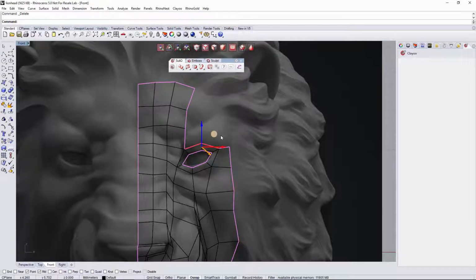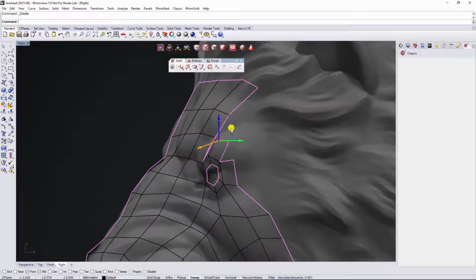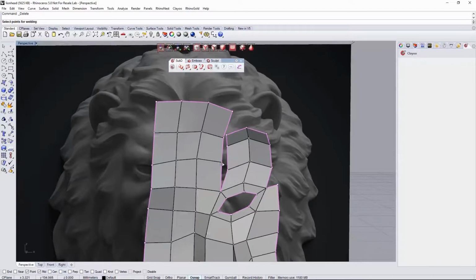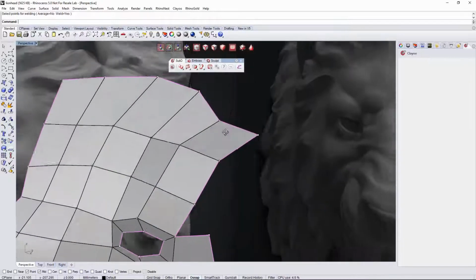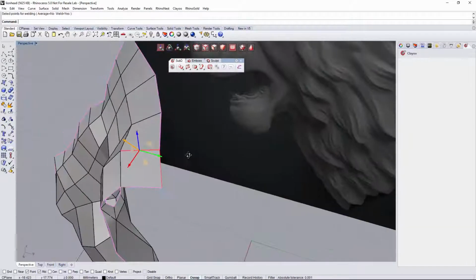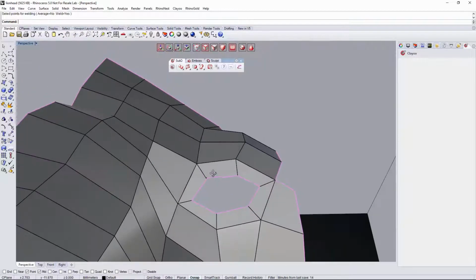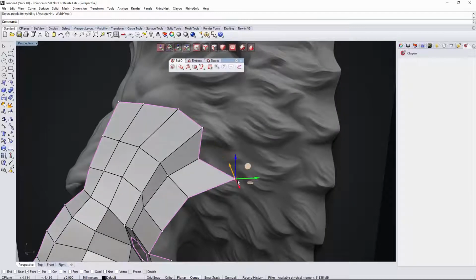It's gonna be easy. So extrude once in here, like that. Extrude twice, 3 times. And make it weld, so Z from this to this, repeat the command, right click from this to this, and repeat again from here to here. Okay, and now we're gonna refine a little bit this shaping here. So from the bottom you can see that this is not taking an organic shape, so just refine that a little bit.